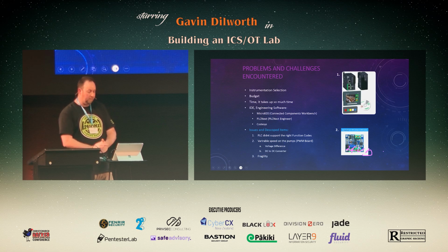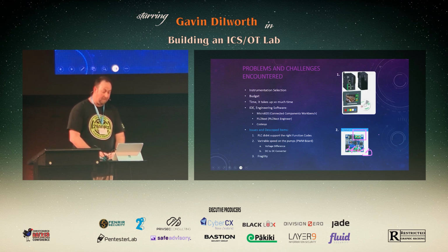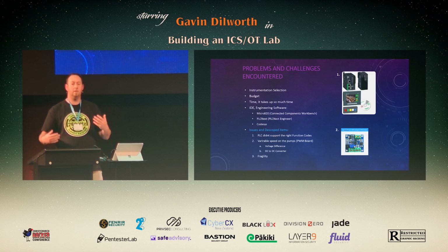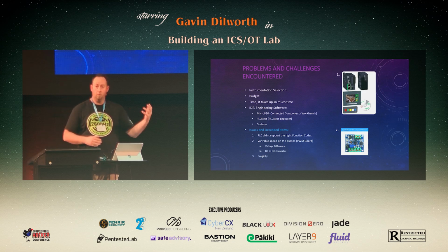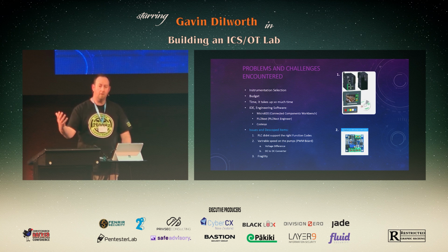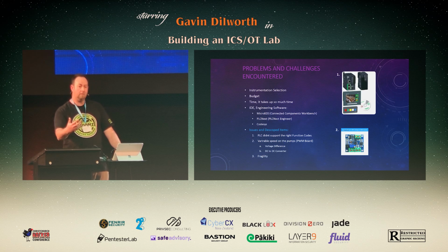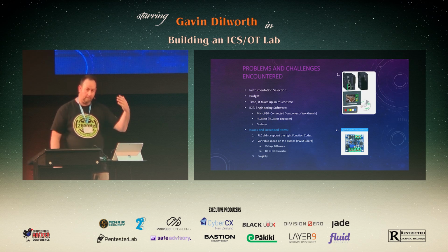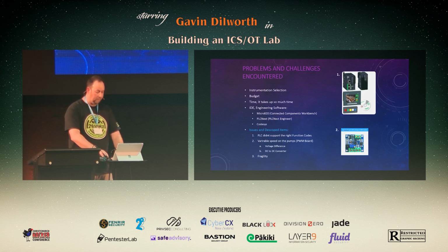What I didn't realise was that to actually power the device, it needed 5 volts, which I didn't have. So that really put a damper on things. It's like, okay, it's not a huge problem. We can fix this. There are things called DC to DC converters. I had a 24 volt DC power supply system. I needed 5 volts. I can buy a DC-DC converter, and then I can make this modulate my pumps.